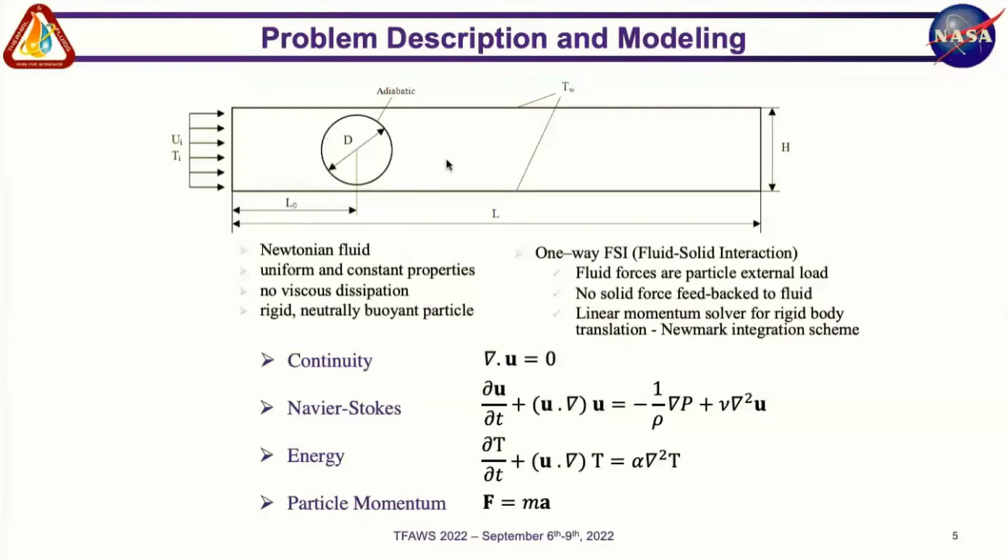To simulate the fluid mechanics and heat transfer in this channel, we have to use some balance equations. Listed here are continuity, momentum (the Navier-Stokes equation), and the energy balance. These all apply to the fluid region. Then you have to add an equation for the momentum transport of the particle itself, which is considered solid. In this case, this is just Newton's second law.